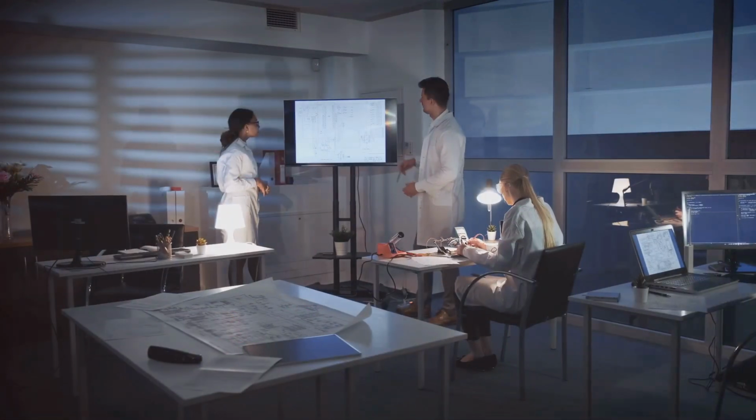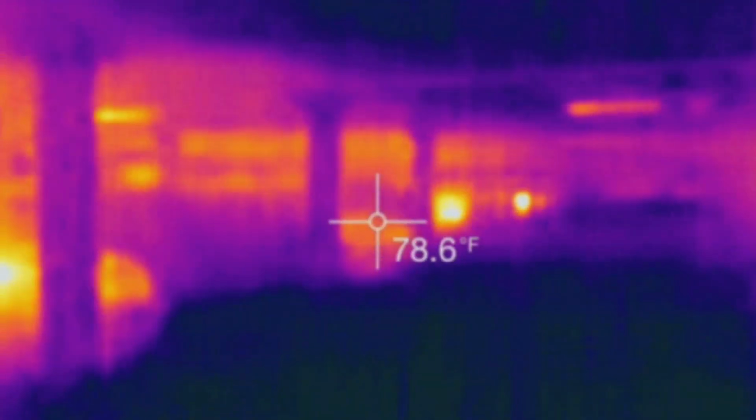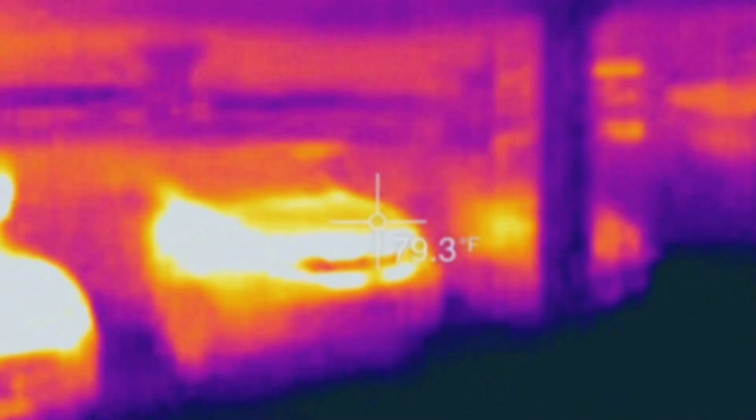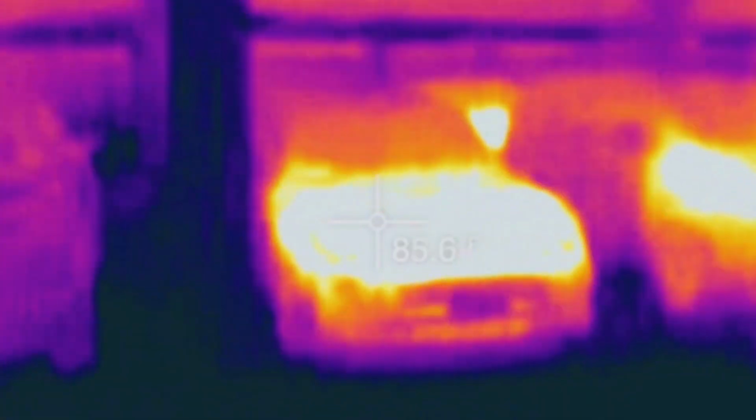Section 9. Illuminating the results: post-processing radiation data. Once the simulation is complete, it's time to analyze the results. ANSYS FLUENT provides a range of post-processing tools to visualize and interpret radiation data. These tools allow engineers to generate temperature contours, radiation flux plots, and other visualizations to understand how radiation affects the system's behavior. For instance, in a combustion chamber, engineers can visualize the radiative heat flux distribution to identify hotspots and optimize the design.